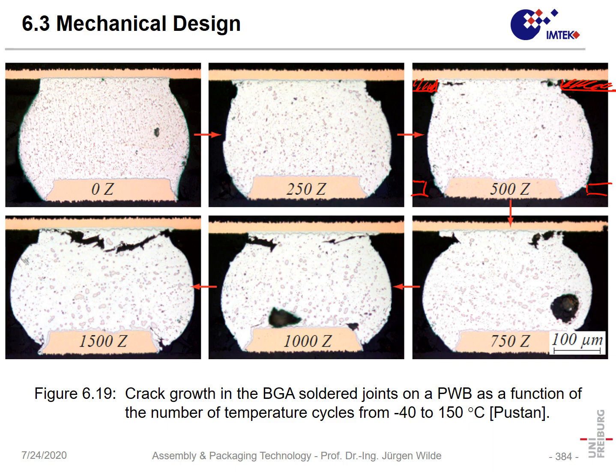The second image is not the same ball, because when you cut it once, you must take another ball. So we took it. What we could find here, there are such kinks on the surface of that solder joints, and such kinks are the first step towards a crack. Here even we see a minute crack, but here in these locations it already becomes larger.